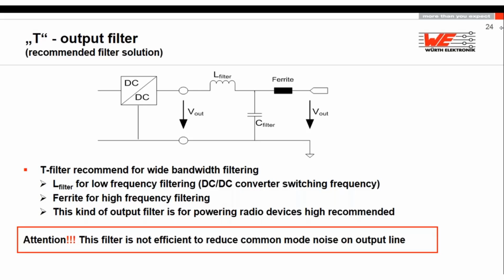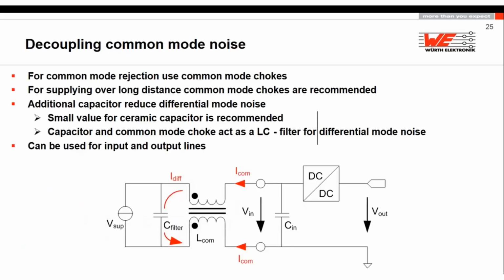It won't destroy your efficiency. Now, if you have something like common mode noise, all this ferrite bead and inductor won't help enough. You have to use a common mode choke as well. But be aware, if you use a common mode choke, you can put the minus to the ground plane in front of the common mode choke. You go to the common mode choke and you put, after the common mode choke, again to the ground plane, because then you make a short circuit of this winding.